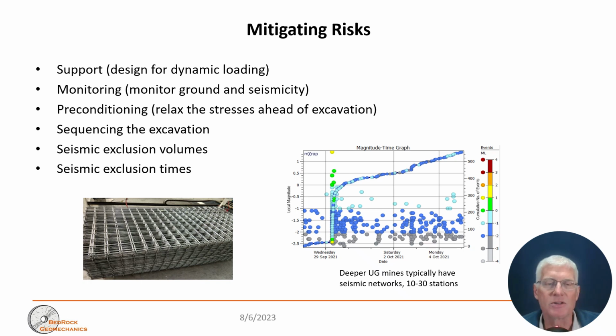Down the bottom, you can see mesh. If you've worked underground, you see mesh all over the place. There are a couple of different kinds. Some are stretchier than others, able to support more load and more deformation. The other things, of course, are rock bolts, split sets, epoxy bolts, and then cables.